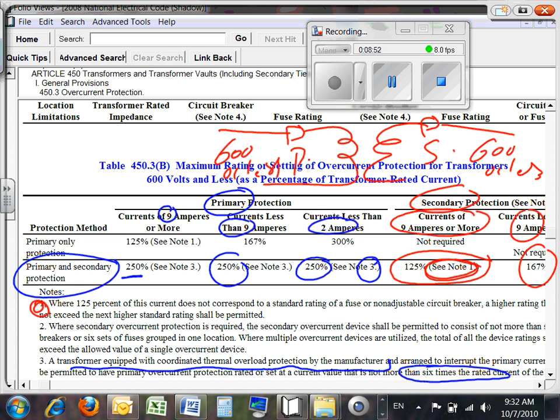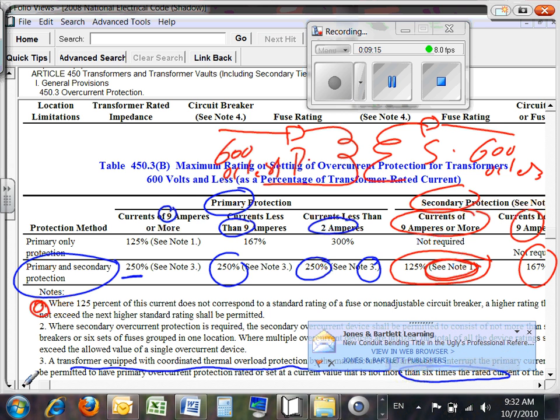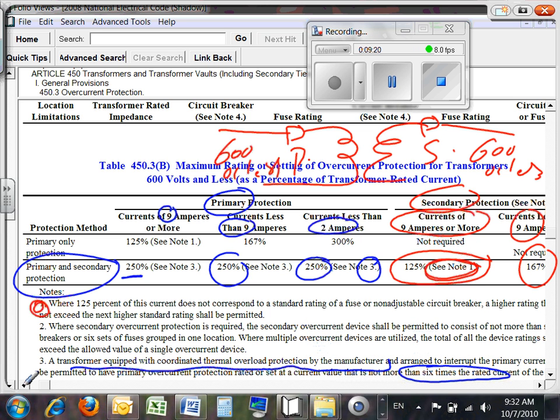So what they do, guys, they put sensors, literally sensors, inside the winding of a transformer, wire these sensors into a relay, and then when you capture the signal in a relay, you can make a decision: either trip if it gets hot inside the transformer, or send an alarm to DJ, saying, DJ, when you have a chance, your transformer is getting hot, go lower the load, do something. There's an action plan. But just keep this in mind. You assume it doesn't exist unless you know otherwise. The assumption is, you're going to be applying this rule unless you know otherwise.